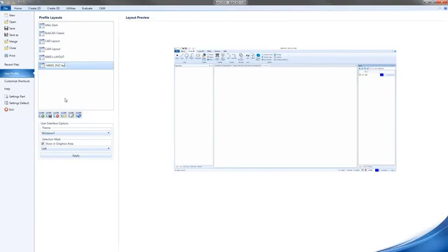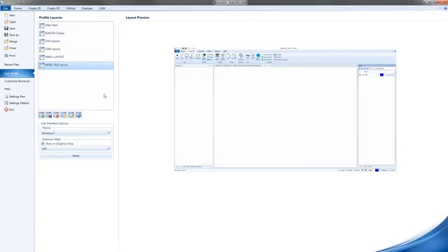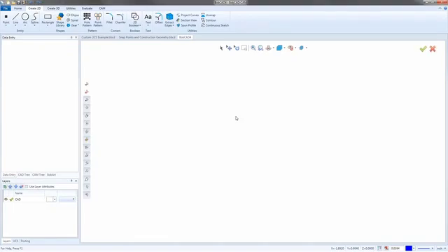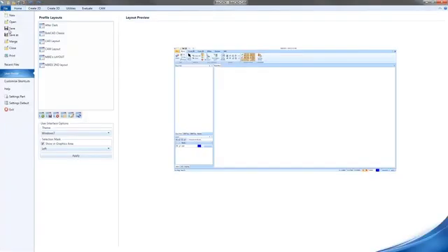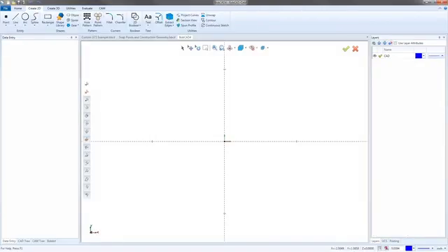All right, so that's Mike's second layout, and then click on it, and right here I can say Save My Layout. Now it's going to override the layout that's currently there, which should be the same one, and we see Mike's second layout. If I turn on the BobCAD Classic again, which should reset back to that one, and then go back to File, User Profile, and choose Mike's second layout and just double-click on it, simple as that, and now my other layout's there.